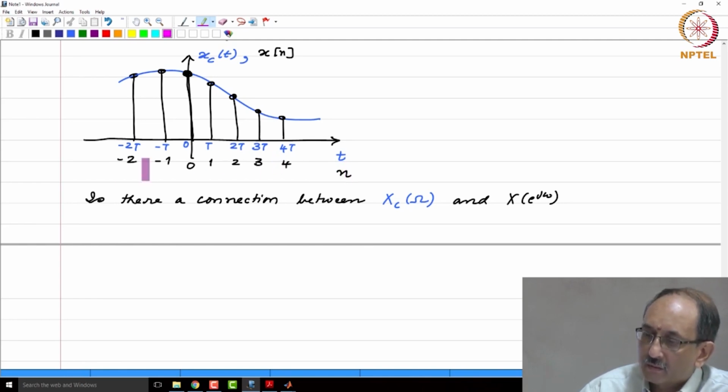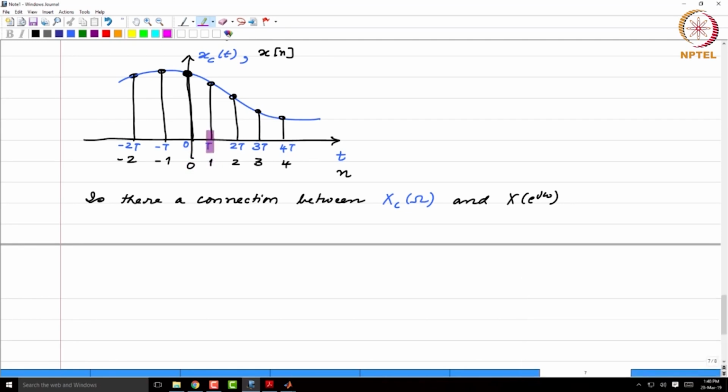So, this sequence of numbers when you plot it versus n does not capture the sampling period, whether T is in milliseconds or microseconds. X of 0 will be at the index 0, the sample at time instance T will map to the index 1 no matter what T is.